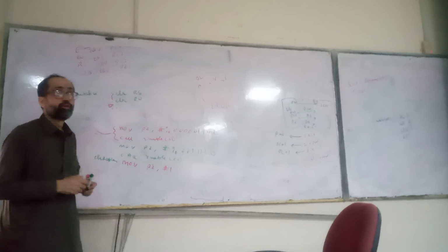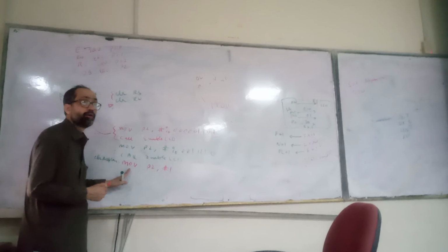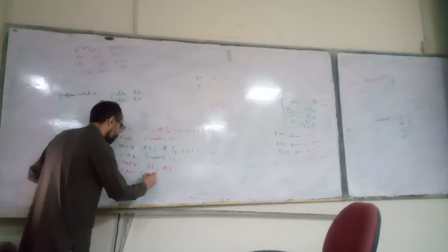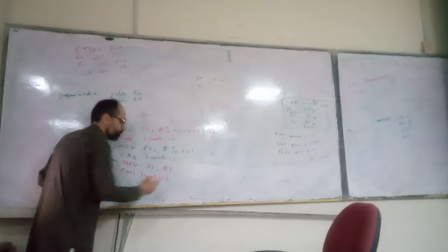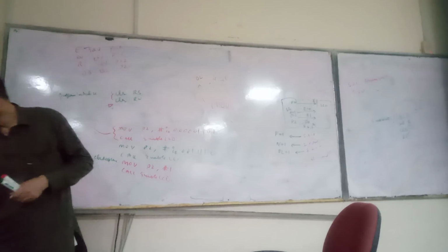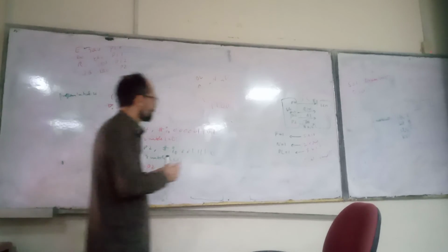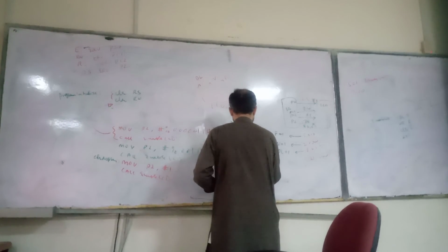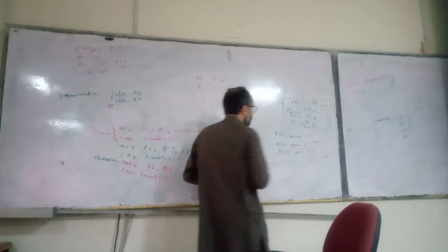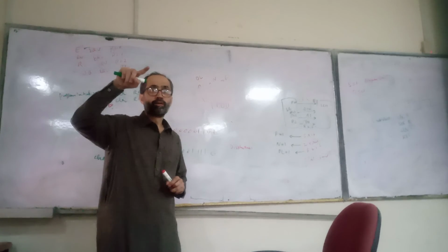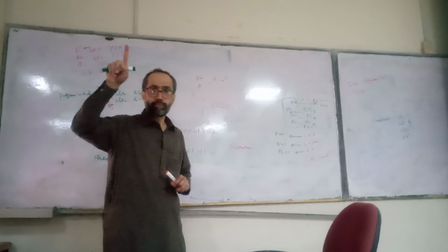But after that, what should we do now? Call enable. So you have to call enable LCD after every command. Call enable LCD. Now display name. We want to display L initially. We should start with L, capital L.